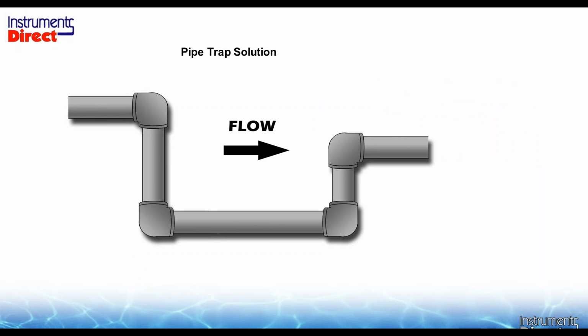The one thing I learned in all the years of working with flow meters is that a closed full pipe is always more accurate and easier to work with than a partially filled pipe. So, should you have the opportunity to reconfigure your plumbing, put a trap in the line and make your partially filled application into a full pipe application. Not everybody has the ability to do that, but if you have the choice, do that. You have much better results, and you have a much wider selection of flow meters to address your situation and your budget requirements.